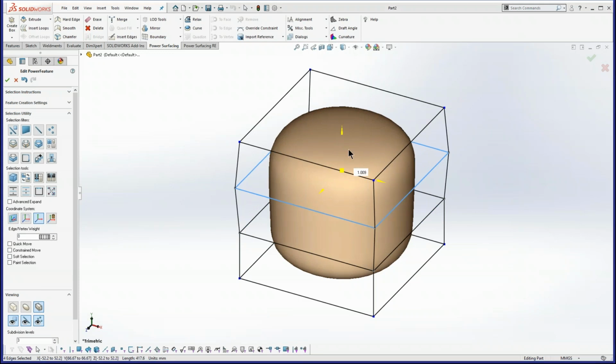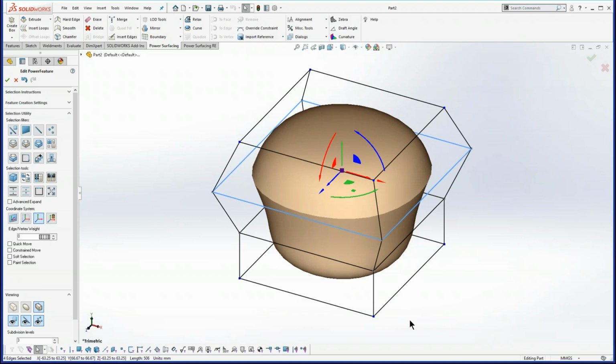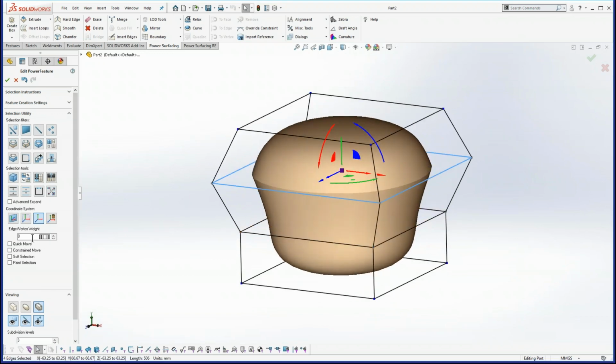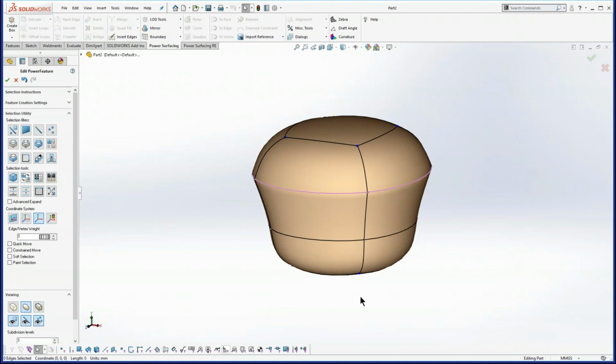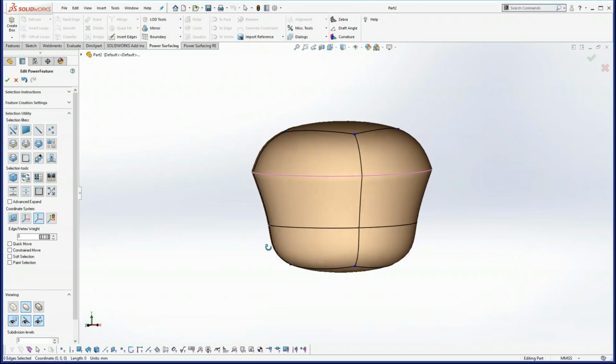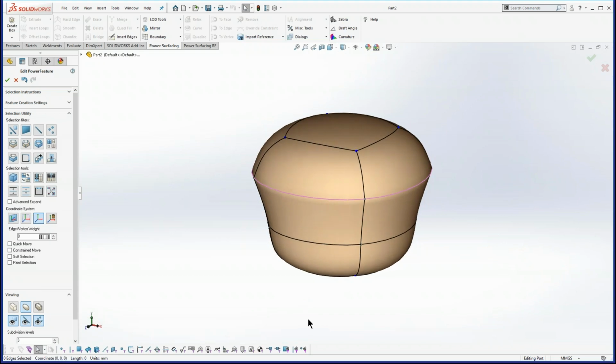So you can easily create that type of car model. In fact, a lot of the car modeling is done with subdivision surface modeling these days. That's what Tesla uses, and that's what a lot of advanced car modeling does, because car manufacturers want to create what are called Class A surfaces, where they're nice, smooth, and continuous, and sub-D modeling creates Class A surfaces by default. If you want to put in an edge and break that continuity, like Susan has done there, you have to do that explicitly by selecting the edge and making it what we call a creased edge. And again, the crease can have 100%, or it can be a softer crease that looks kind of rounded. And you can also put a crease on vertices as well, a weight.